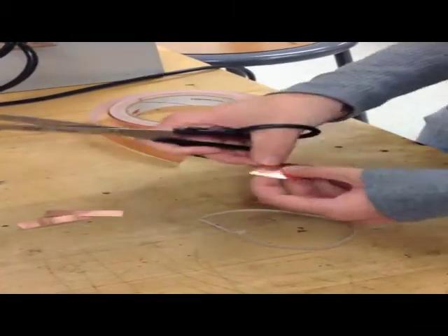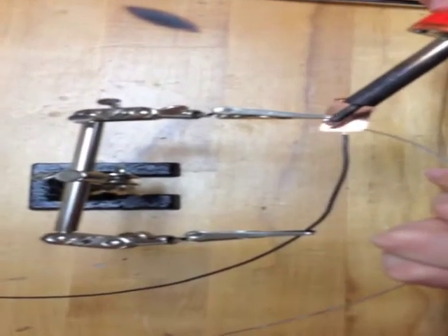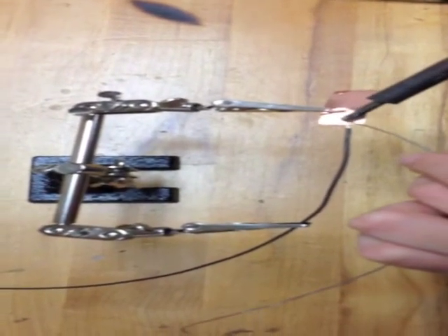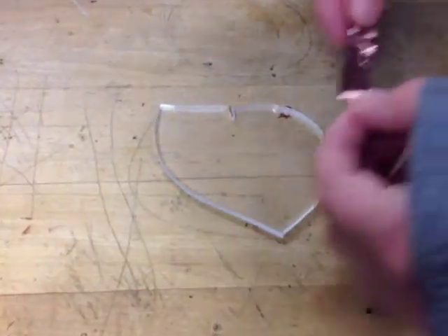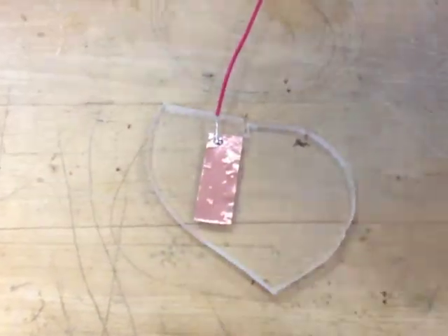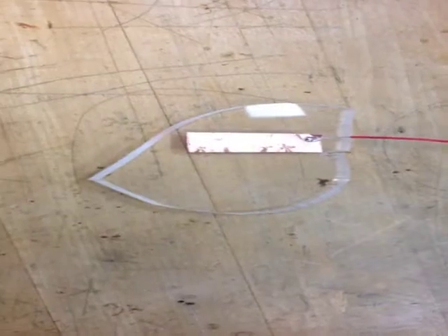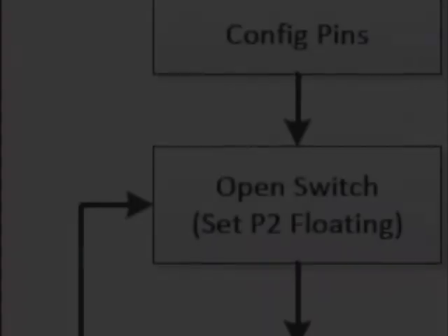To build the circuit, we began by building a parallel plate capacitor. We got 2 strips of copper, soldered wire to them, and stuck them onto an acrylic backing next to each other. That completed the building of the capacitor. Then, we assembled the circuit according to the schematic and connected it to the Arduino board. The Arduino board sends out the square wave at node P0, it discharges the capacitor in the peak hold detector at node P2, and reads the output of the entire circuit at node P1.